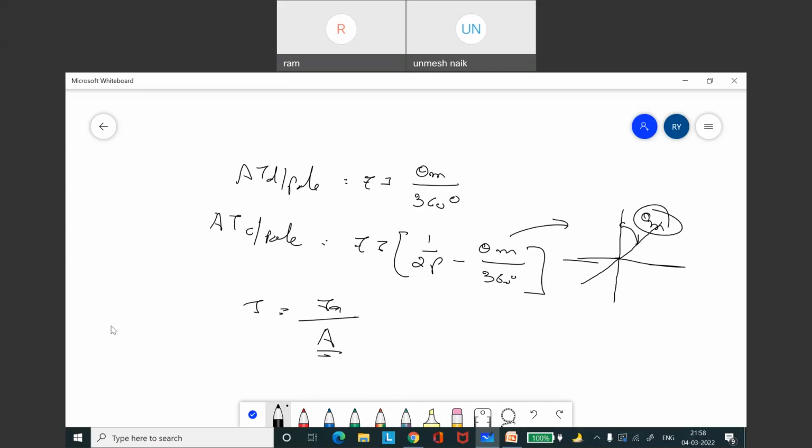Generally, the demagnetizing effect can be nullified by increasing the field current, or by increasing the number of field turns. The cross magnetizing effect of armature reaction can be compensated by using compensating windings. These compensating windings are placed within the pole itself.